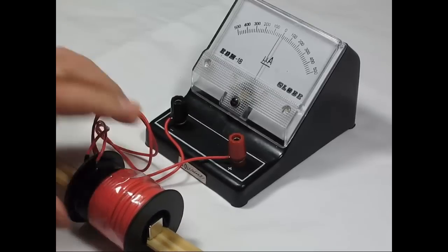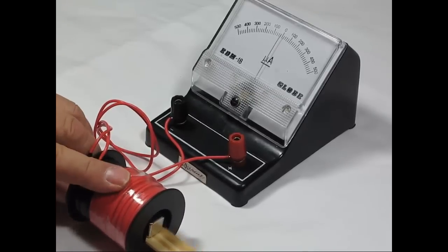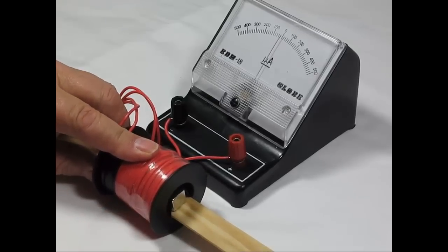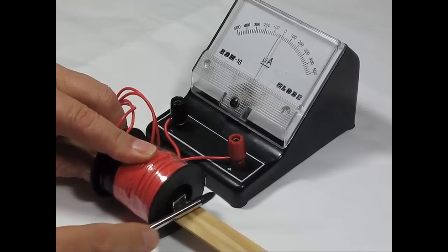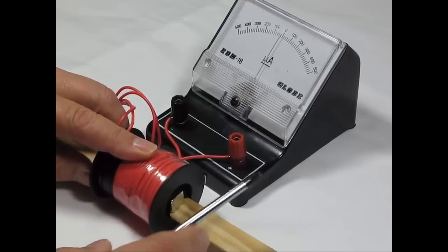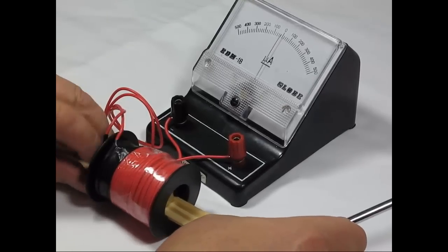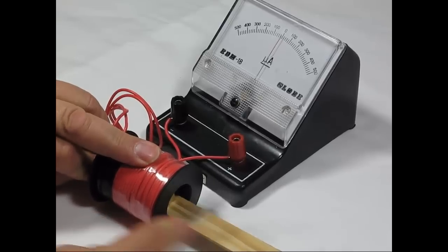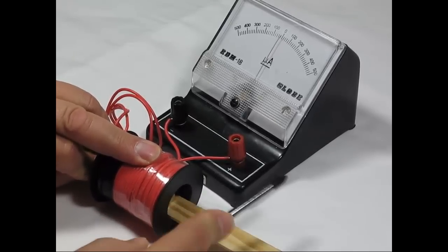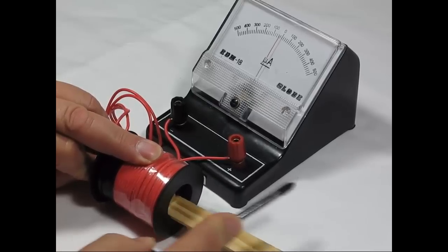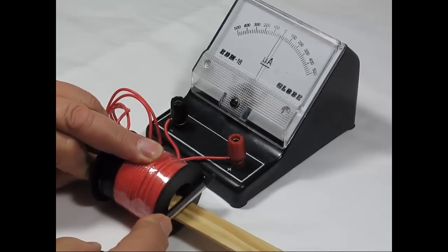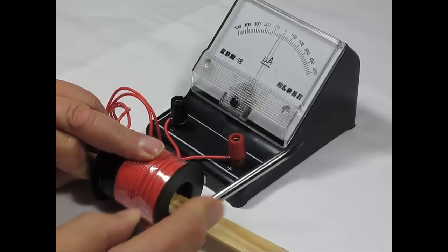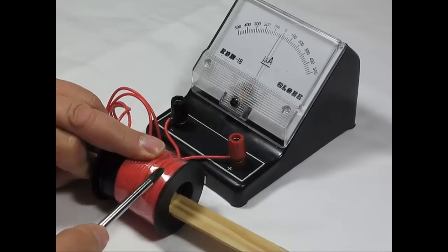Now another phenomenon I want you to notice, I'm going to hold this as stationary as I possibly can, and I'm going to disturb the magnetic field with a screwdriver. Whoop. See how hard that is to get off of there? So I'm going to hold this down a little bit better. And watch the needle. Can you see the needle moving? The needle is moving because when I bring this ferromagnetic material in here, it is intensifying the magnetic field, because the magnetic field moves with less resistance through ferromagnetic material than it does through air.